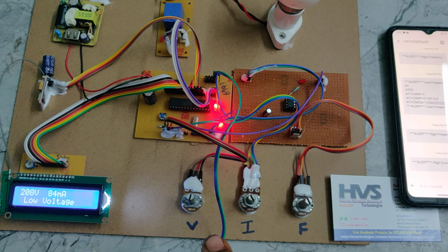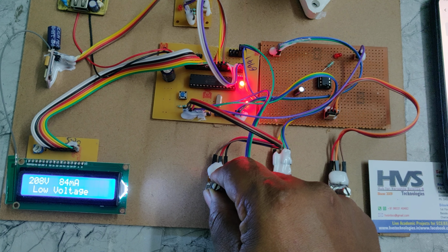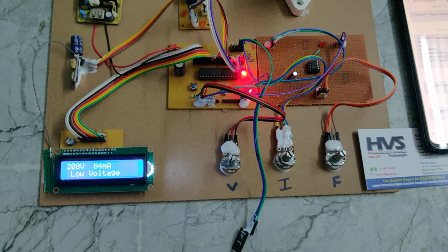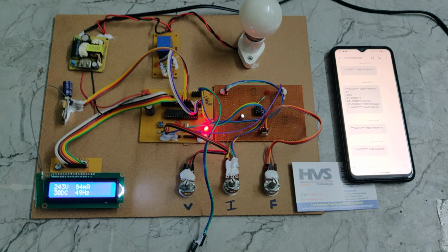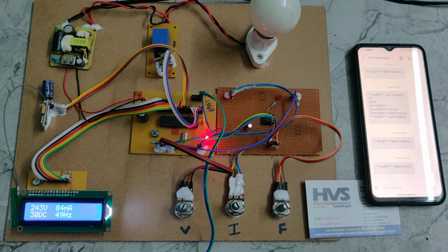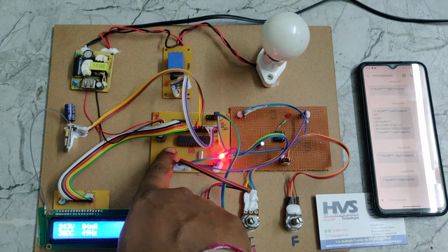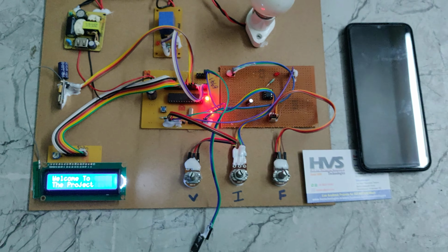Here there is no auto reset, as in electrical work we don't prefer auto reset. Why? Because while repairs are being done, if auto reset happened, the person taking care of the repair section may get the voltage, and that leads to shocks. That's why we disable it. After everything is set right, seen on the screen, you can reset the system.